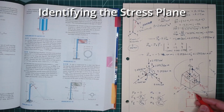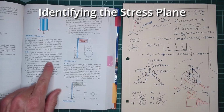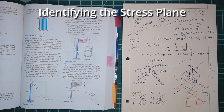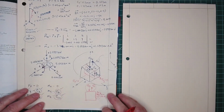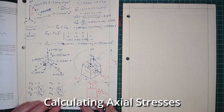Once we look at this, we can combine these up into a single axial stress. We can combine these up into a single shear stress, and then we can do our Mohr circle to get to our sigma max and our tau max. Okay, so we're going to talk a little bit more about getting to that point right here. So the next thing is calculating up these stresses. We've already got the roadmap for what we need to calculate. So let's take a look.